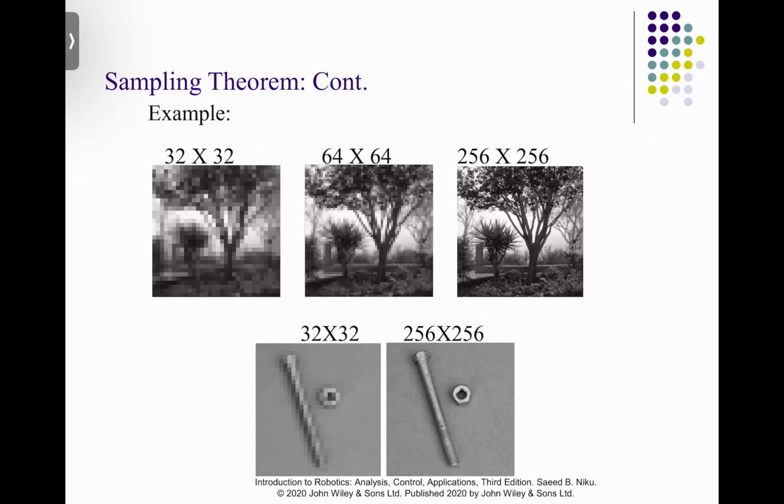Yeah, you can capture the whole signal, but the problem is you have this analog signal that is continuous, but your device is digital, which means you cannot capture that entire signal unless you have very high resolution, high-end electronics. Finally, computers are digital, so you have to sample.